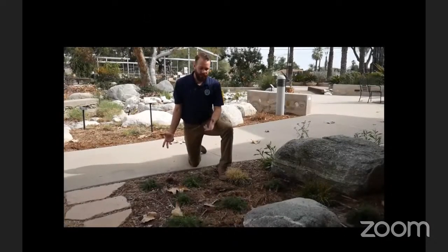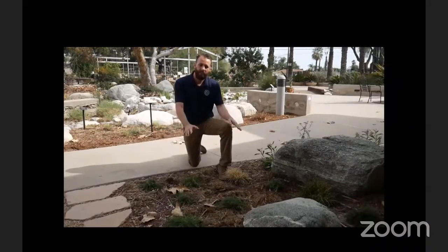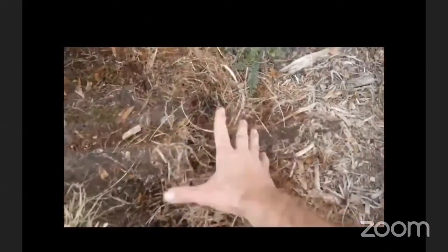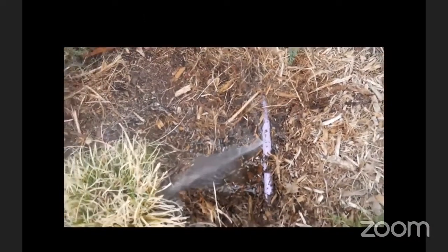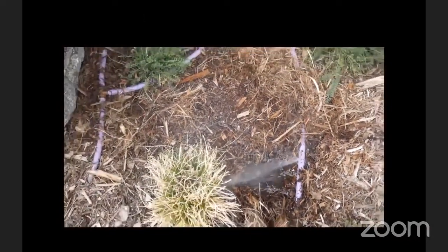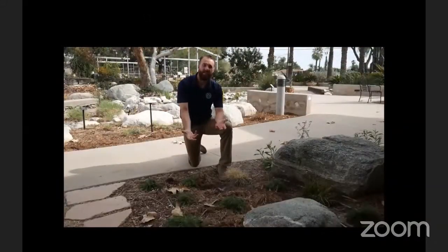Okay, now that we've turned on our system, we walked around and we hear in this area, something that sounds a little different. This is where we know to start looking for the leak. Because drip tubing is typically covered in mulch, you can't visually see. So as we peel back, found a leak. This is a tiny tear in the tubing, which could easily be done with your shovel when you're out there gardening. But since it's hidden underneath the mulch, we wouldn't have known unless we looked.